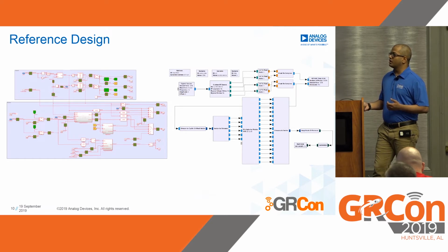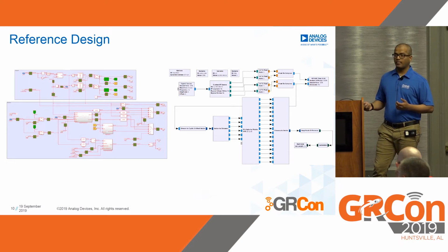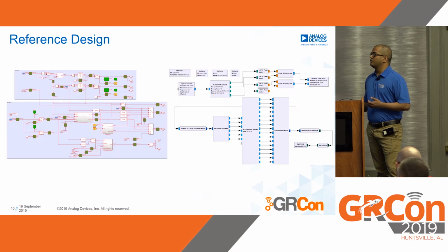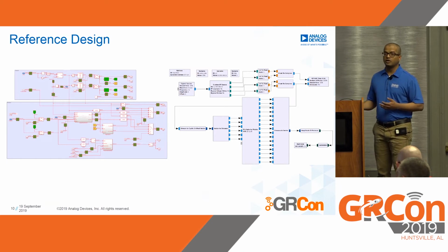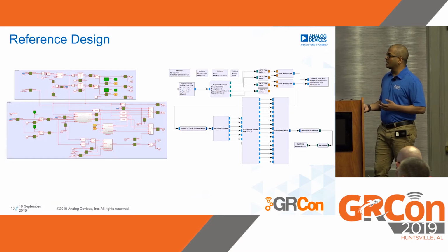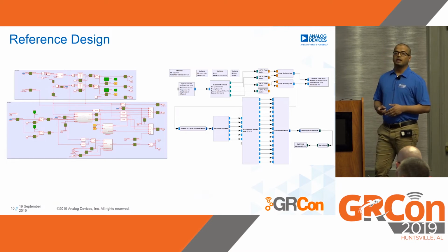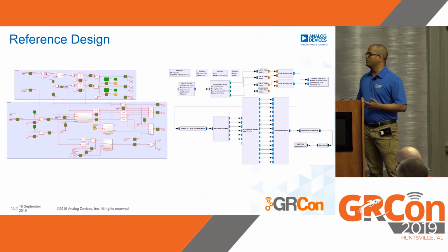So the integer delay estimation block receives both a reference waveform, which is looped back within the IP itself, and the RX waveform. That computes the integer delay, which is fed to this align streams block. A status value gets written, which says that the integer value has been computed, and the custom IP source in the gr-iio flow graph reads that register value to start the process of estimating fractional delay. And the final block here, the correlator, writes the value of fractional delay as well as a status value that fractional delay is now available for the IP to correct for fractional loopback delay. So in this way, the two pieces communicate with each other.